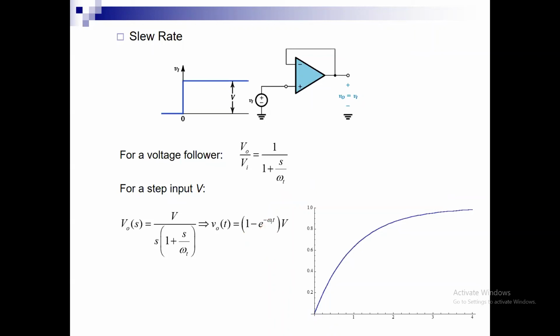It will have some slope. Its maximum slope is here, which we just calculated, and I have to see if my natural slew rate, which is the criteria, is exceeded by this slope. If it is greater than the slew rate, then I will fail, else I will be fine. For example, if the natural slew rate is this example SR1, do I have any problem here? No, because my slope is lower, right?